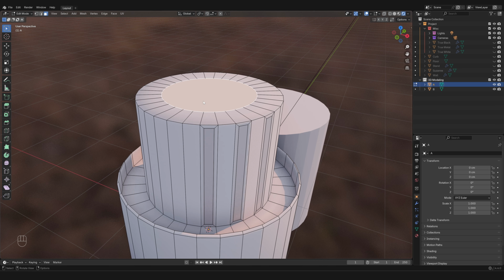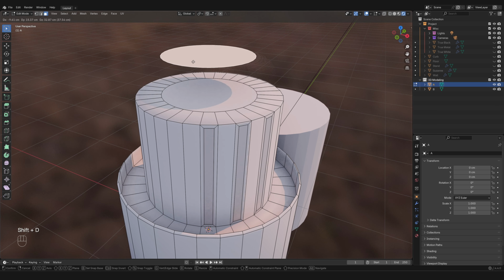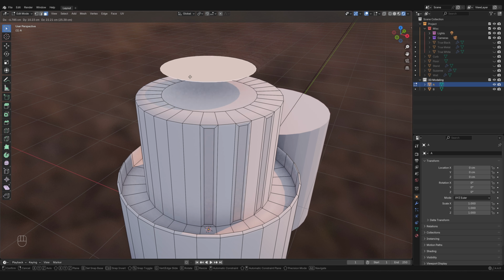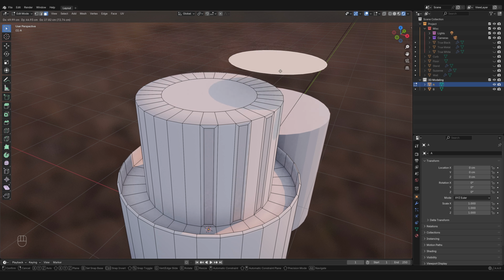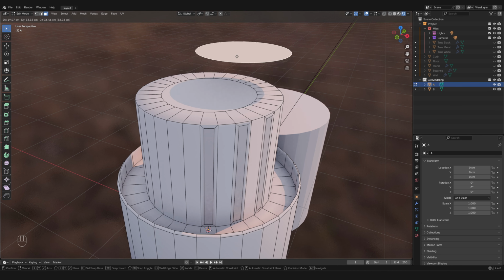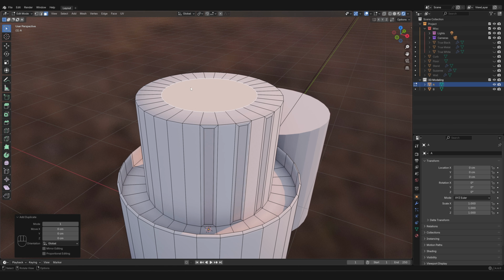Okay, moving forward with a face selected, we have the usual Shift+D duplication command, which will make a copy of that face, edge, or vertices that you have selected, and then you will be able to place it around. And now if you right click, beware that that face still exists. You just have let it snap in place.